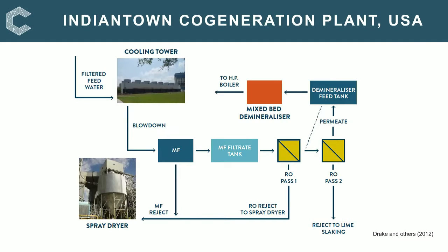And using a reverse osmosis system also gave it the flexibility to use different combinations of make-up water for the cooling tower. These are water from the nearby creek, municipal wastewater, and some highly saline groundwater from the wells. And eliminating the brine concentrators has resulted in a reduction of the parasitic power consumption.